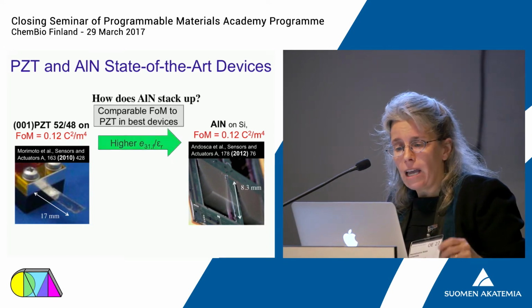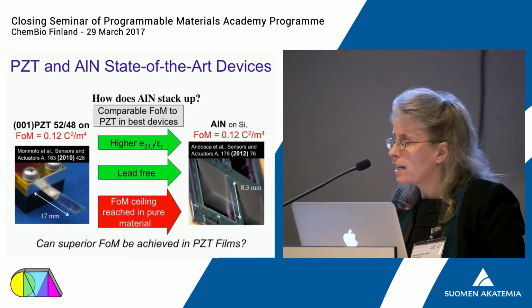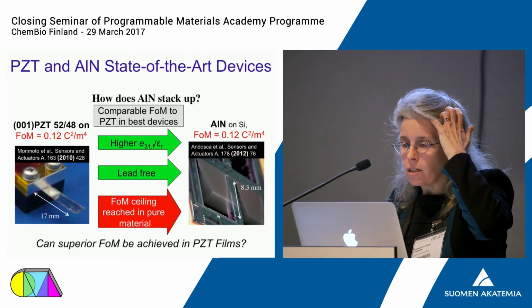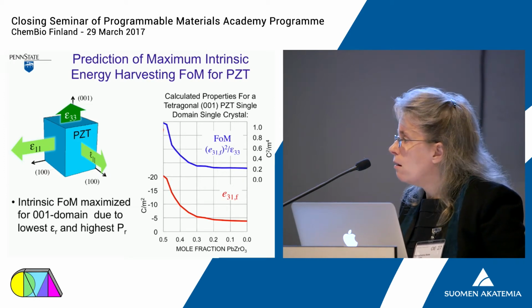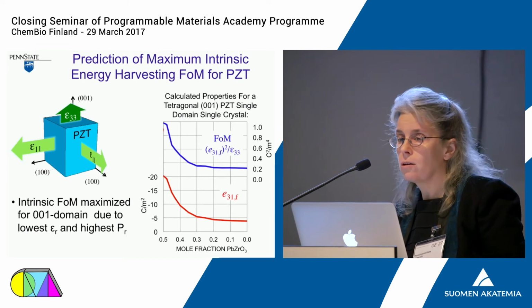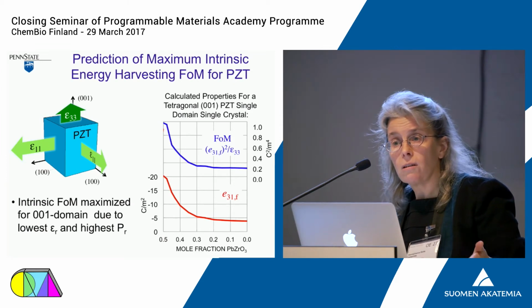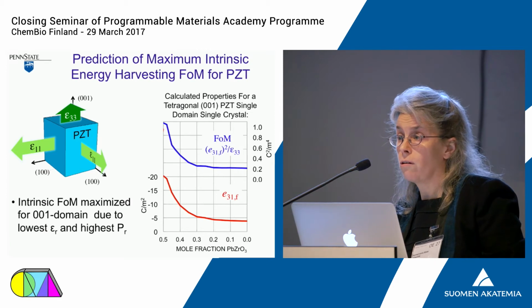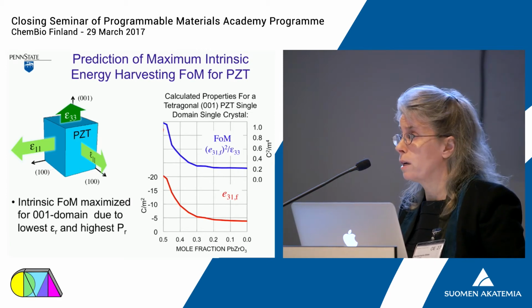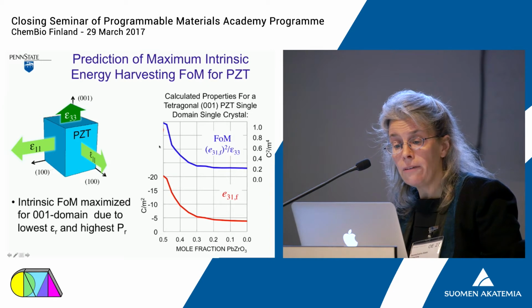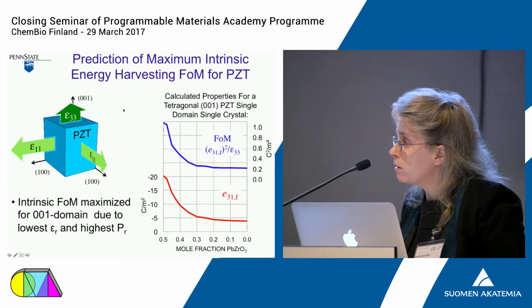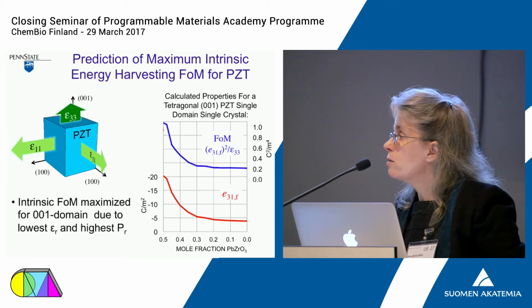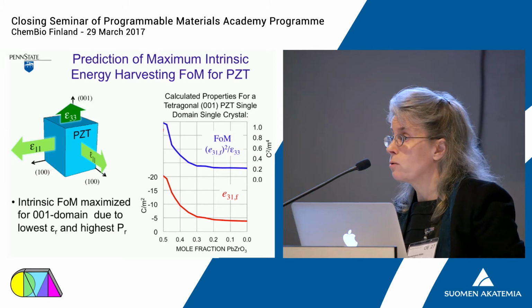And so we had a look at whether we can actually do better in a lead zirconate titanate film. Our approach was to recognize that all piezoelectric materials are inherently anisotropic, which means that the dielectric and the piezoelectric coefficients are a function of the direction in which they are measured in these solids. And if I take a 100 oriented lead zirconate titanate material with the polarization direction out of plane, that gives me the smallest dielectric constant and the largest piezoelectric coefficient.